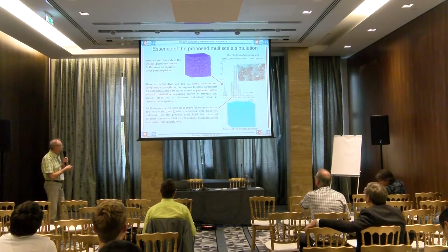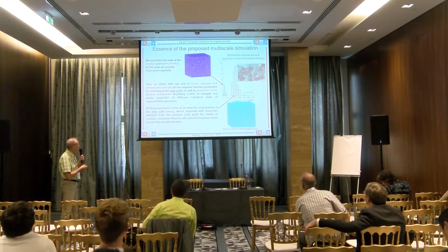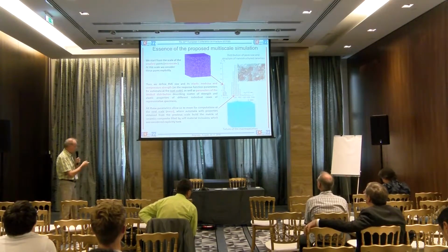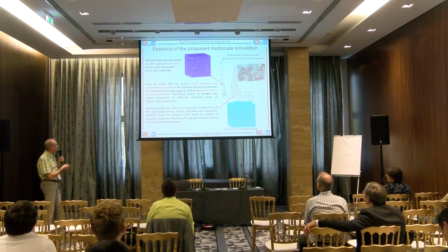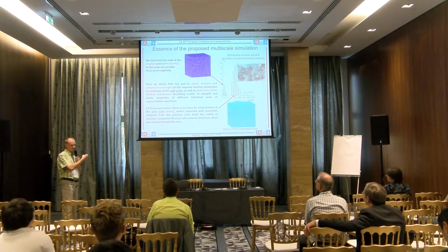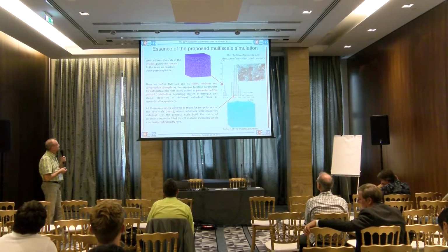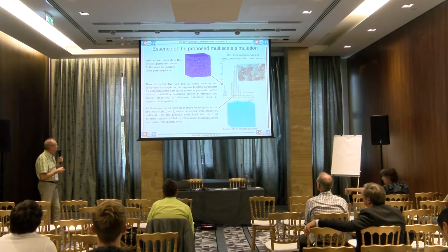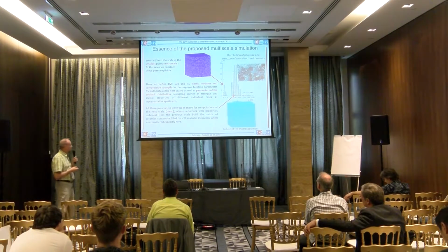I will show an example of such curves a little bit later. So from this curve, we can get elastic modulus of such a specimen and compression strength. Just the elastic modulus is the inclination of the line, and the strength is the highest point. With these two parameters, we can also get the Poisson ratio. These parameters will scatter for different spatial positions of pores. So we have these parameters and the parameters of Weibull distributions of them.